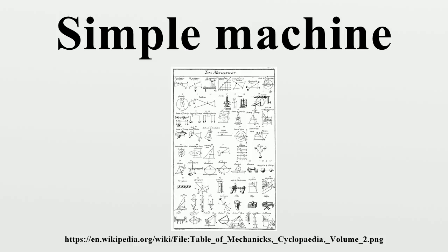This realization shows that it is the joints, or the connections that provide movement, that are the primary elements of a machine. Starting with four types of joints: the revolute joint, sliding joint, cam joint and gear joint, and related connections such as cables and belts, it is possible to understand a machine as an assembly of solid parts that connect these joints.